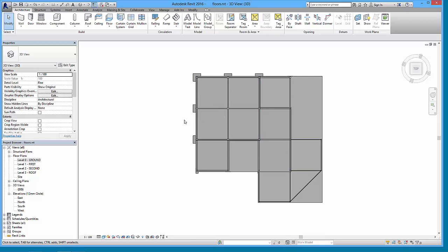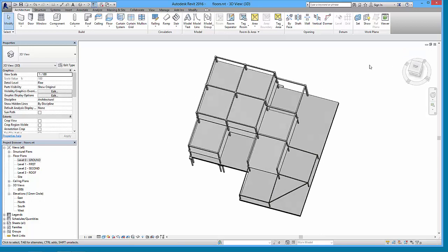So on the west elevation we're going to have some curtain walling. I'll also put some brickwork around here, and we'll put in this crisscross of concrete retaining wall or structural wall in this core area as well. So we'll cover several different options. We won't cover all of it. We'll have done a bit more in class, but this is again just to remind you of the process. So back to the 3D view,